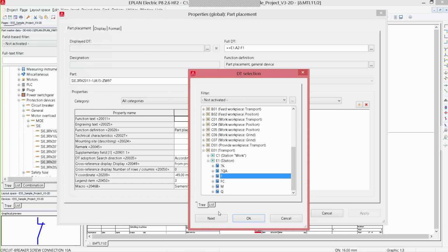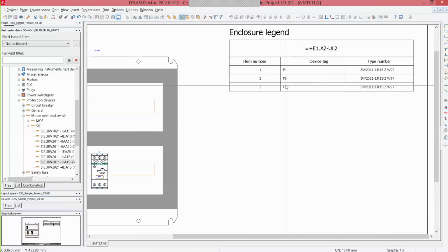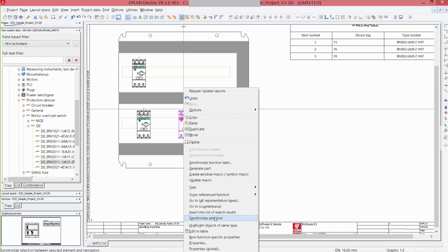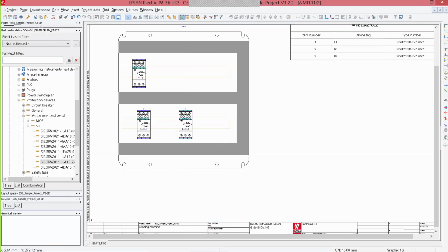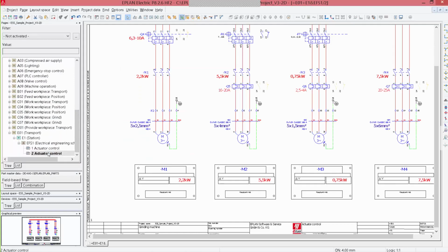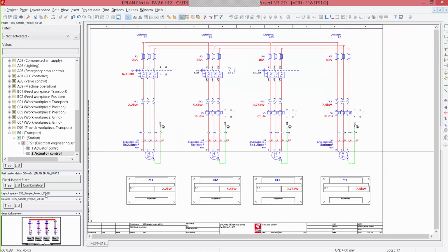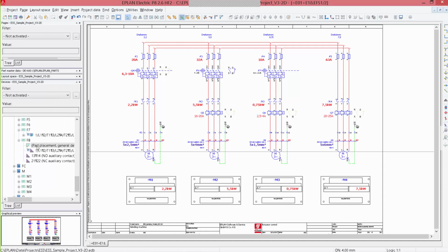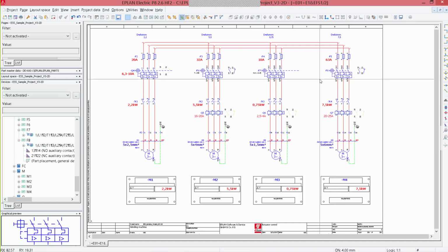So in this case, we'll take F8 and OK, which is here. So I have F8 with the same type number here. What is now important is if I want to utilize the same parts also in my 2D design later on, I need to basically open again the page where I want to place this one, which is here. We see already I prepared an empty slot for this. And based on the F8, which I have in my device navigator, I simply just drag and drop. Again, we have a single source of data through the Eplan platform, and of course this is very simple to utilize between the different types of representations. So regardless of where you are in the project of detail design, in single line or in multi-line or in the 2D layout, it's all seamlessly utilizing the same environment.